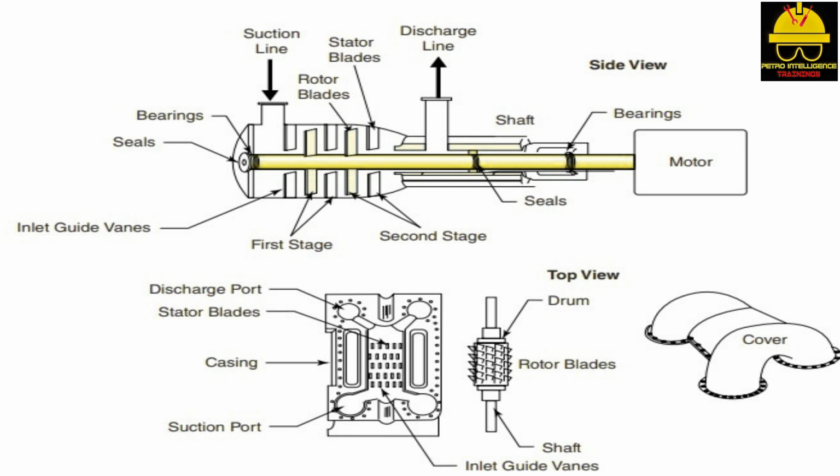Pound for pound, axial compressors are lighter, more efficient, and smaller than centrifugal. A 23,000 horsepower axial produces as efficiently as a 25,500 horsepower centrifugal. Even so, axial flow compressors are not as common as reciprocating and centrifugal compressors. One main use of axial compressors is in gas turbine applications.